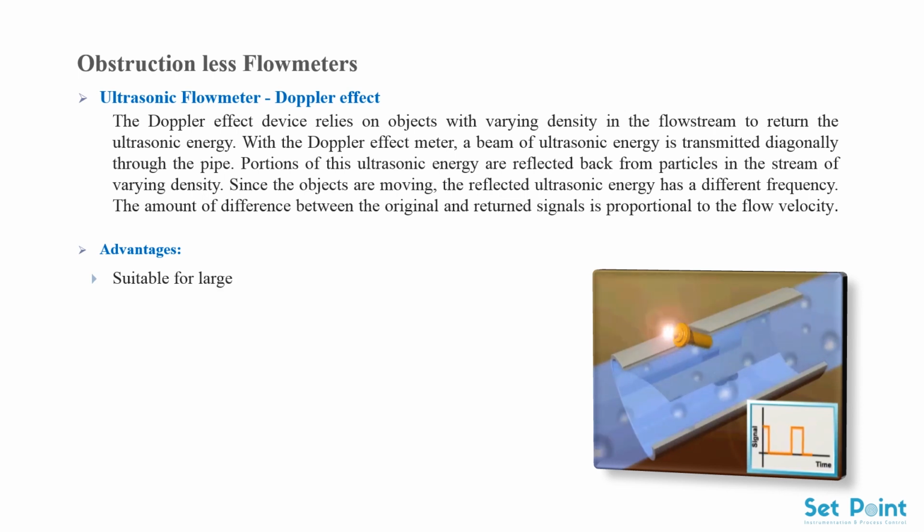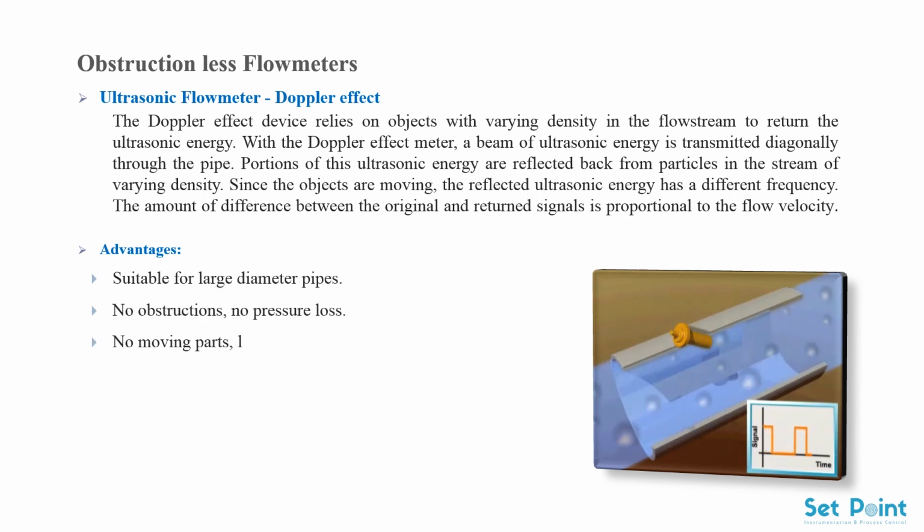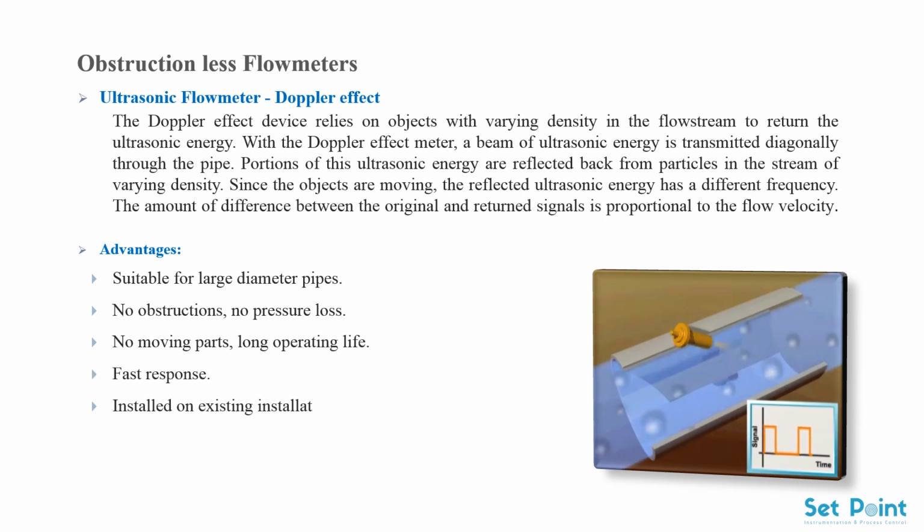Advantages. Suitable for large diameter pipes. No obstructions, no pressure loss. No moving parts, long operating life. Fast response. Installed on existing installations. Not affected by fluid properties.